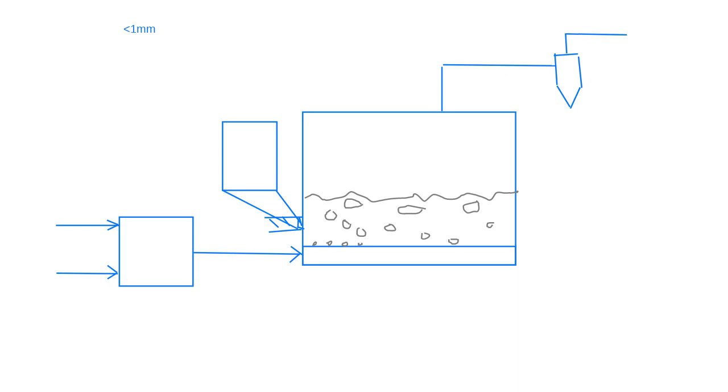Okay, so there you get dust, but you will take off your solids from the bed with an overflow from the fluidized bed, and that'll be the main thing, your dry solids, and then from here you can mix the dust that you've collected back into the solid material. And that's about it. So this might be operating at 1,000 degrees C, like in the previous example.